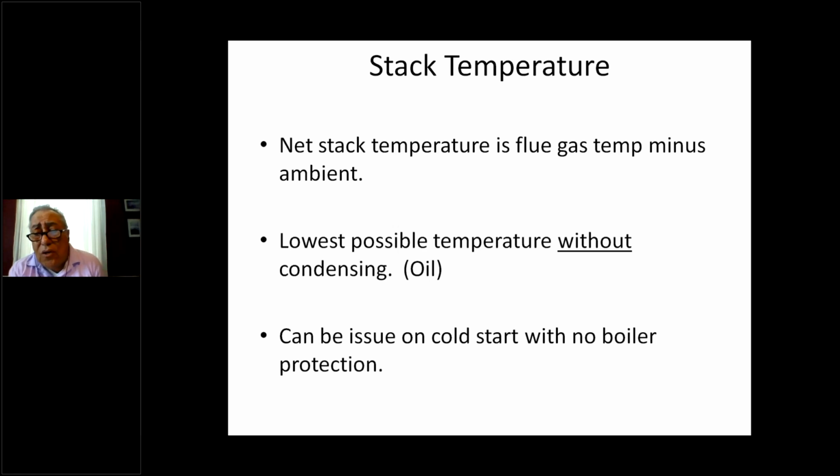This also can be a problem with a cold start boiler with no boiler protection. If you have a cold start boiler in the middle of the summer, the boiler is at ambient temperature, and you start it up and start doing your combustion testing. Until that boiler warms up, if your circulator is running, you're putting cold water into the water side, and you've got the fire side with your higher temperature, and you're condensing in the flue passages, which is not a good thing. Boiler protection is really simple: you hold out the circulator until the boiler gets up to temperature. But if there's no protection, then this condensing, and again, this is with oil, can be an issue.